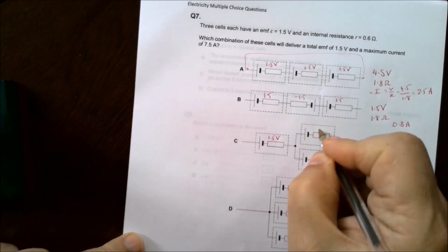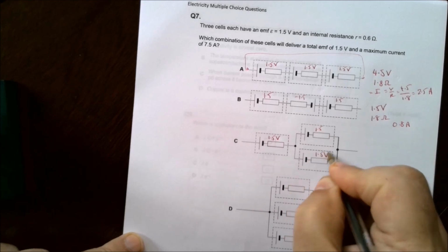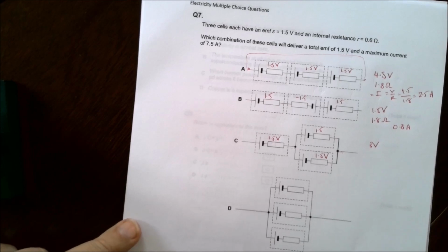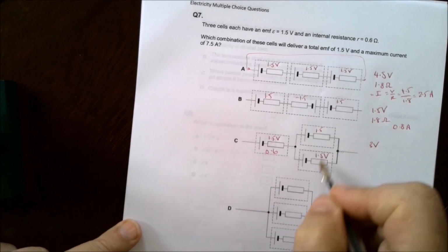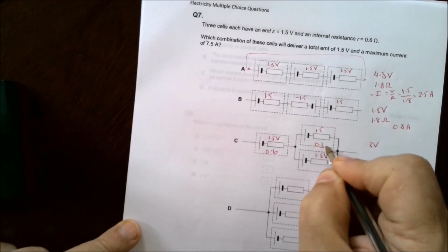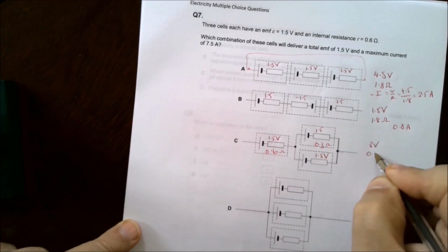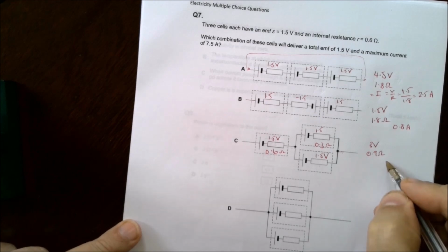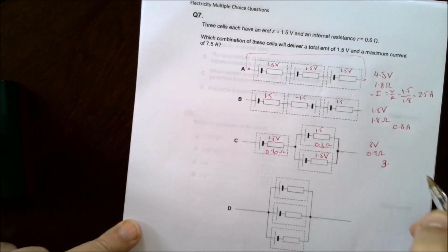If you look at this one, life's getting quite complicated. This is 1.5 volts, these are both 1.5 volts as well, it's all facing the same way. So the potential difference between there and there is 1.5, so this is giving you 3 volts. You can go through that and work out that this is 0.6, this is 2 0.6 in parallel, which gives you a total of 0.3 ohms. So the total resistance of that circuit is 0.9 ohms. So that gives you just over 3 amps as the maximum current.